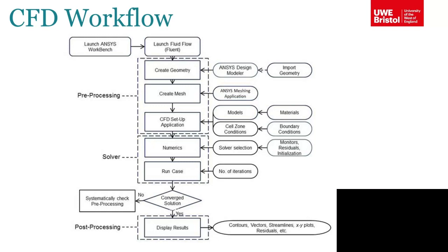You have to do some cleaning because the algorithms that you use to draw the structure are not the same in both software. So a software like Rhino can be used to clean the drawing made in another software to be suitable for a CFD tool, without duplicates, without holes and so on.